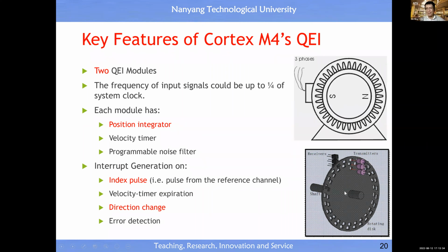What is a digital sensor? So we use this motion sensor as an example, okay? It's this device which will transform rotational motion or linear motion into square wave, right? So in particular, we have 3 pairs of light emitter and light detector, right? 2 pairs of them are needed for us to know the value and the direction.